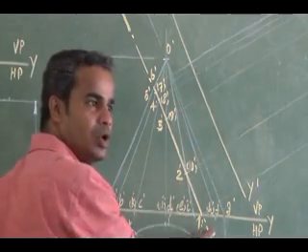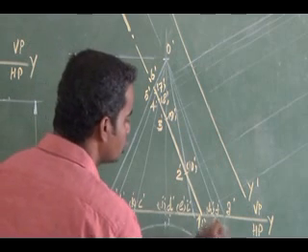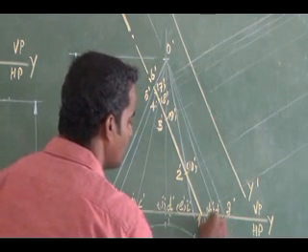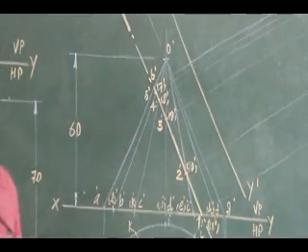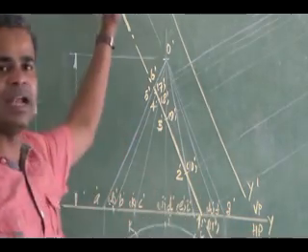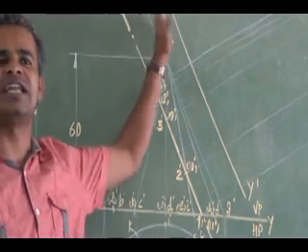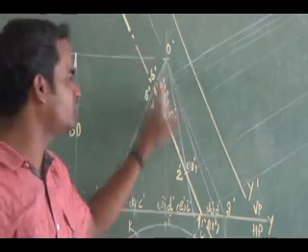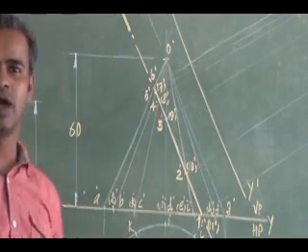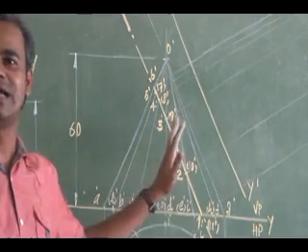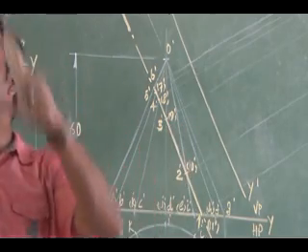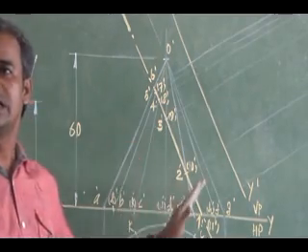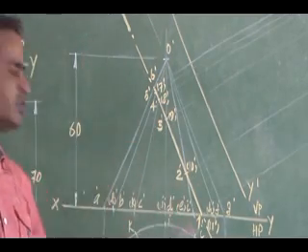The base again. So that is a hidden base point. So that is my 11 dash. So 1 dash and 11 dash on the base, remaining 9 cutting points on the generators. 5 of them are visible cutting points, 4 of them are hidden cutting points. Totally it cuts 9 generators and a base. Totally 11 cutting points. If it cuts a base, I will get 2 cutting points. Similarly, it cuts the generators totally.